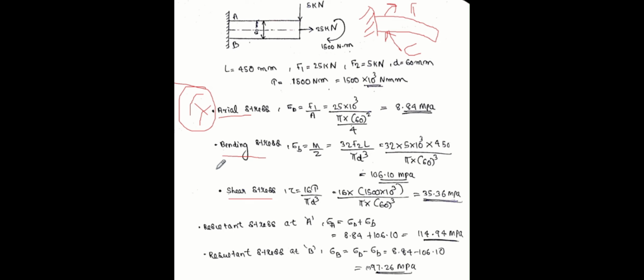The basic convention is that tension is added and compression is negative. So if you take the resultant at the top part, the axial load plus the bending stress, the top portion due to the bending load will have tension, so the stress due to that is added to the axial load. That's why there is a positive sign between the stresses.